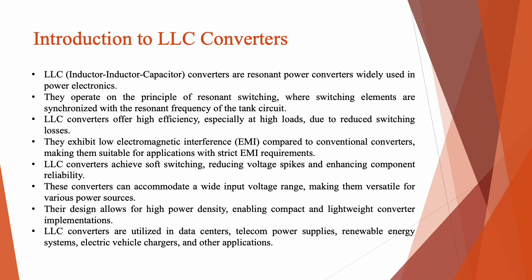Also, they exhibit low electromagnetic interference compared to conventional converters, making them suitable for applications with strict EMI requirements. Also, they are able to achieve soft switching, reducing voltage spikes and enhancing component reliability. They can accommodate a wide input voltage range, making them versatile for various power sources, and they allow for high power density, enabling compact and lightweight converter implementations.